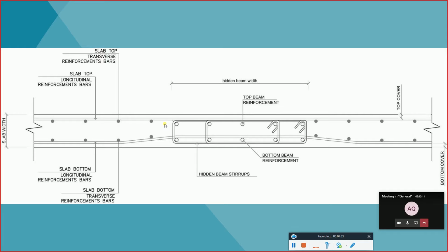Normally, if you remember from taking any of your design courses, the depth of the beam is more than the width of the beam, and that's due to the loading condition and the stiffness. If you remember, while designing the beam it is very important to check the deflection, and it's very important to check the bending moment and shear forces.